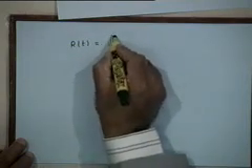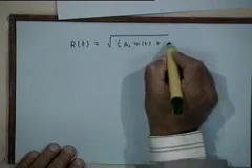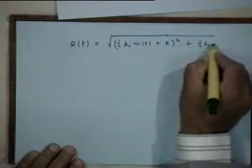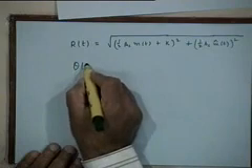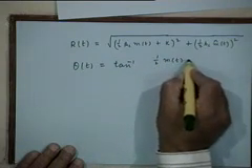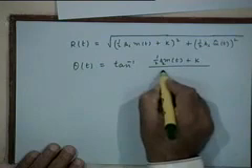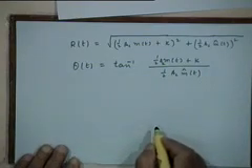So here R(t) is the square root of [half A_c m(t) plus K] whole square plus [half A_c m hat(t)] whole square, and theta(t) is tan inverse of half A_c m(t) plus K upon half A_c m hat(t). Inverse of this?